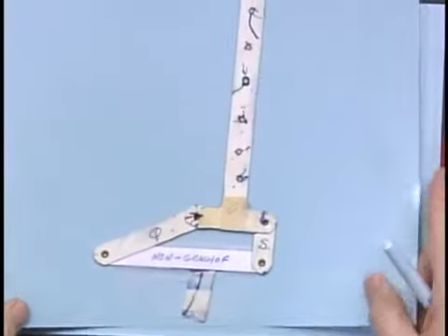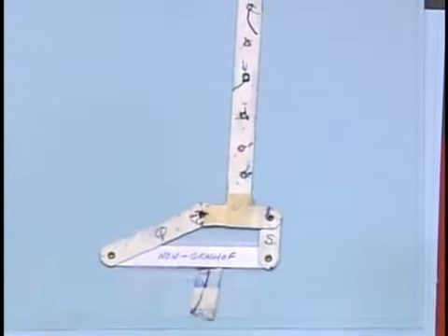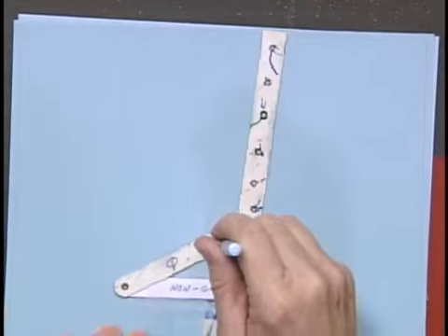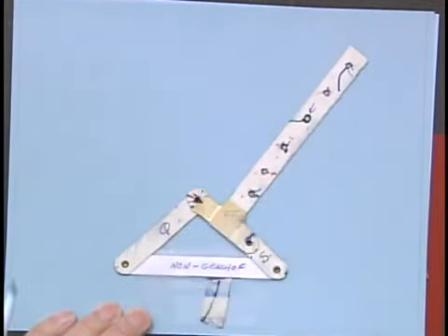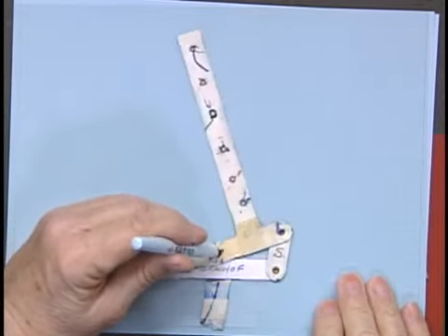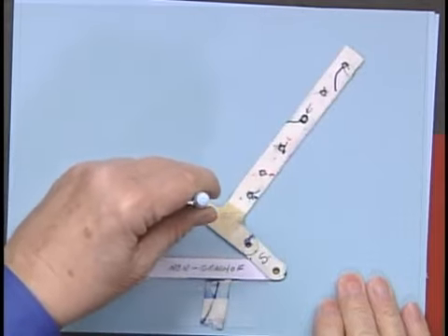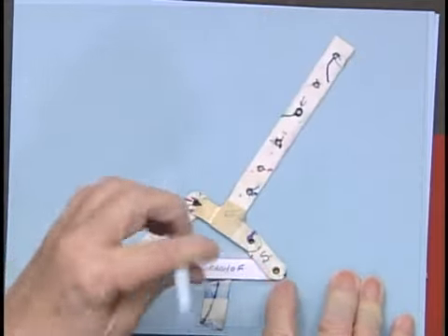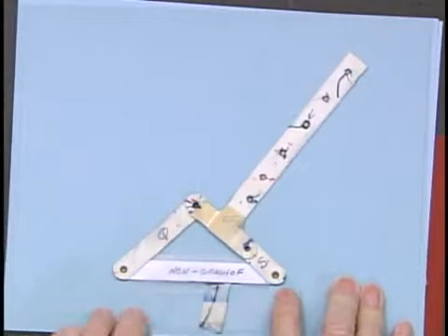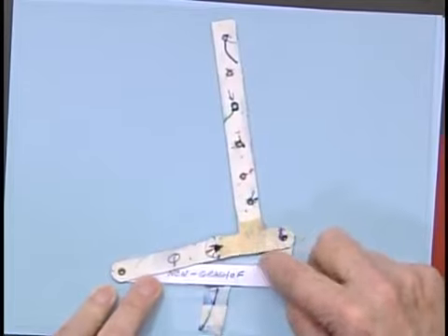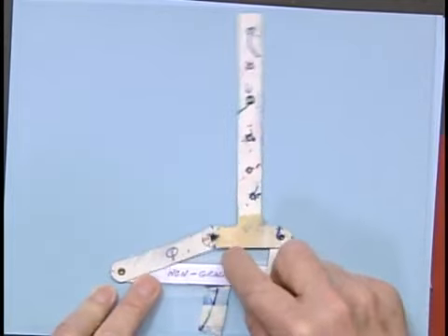Now let's take a non-Grashof linkage as an example, also made in cardboard, and see what we can do with it. Well, let's determine to your satisfaction that it is in fact non-Grashof. There, my hand's in your way, but if I do this with my non-dominant hand, you can see that I'm going to a toggle, so that cannot go any further that way, and if I go this way, it's going to toggle over here again. So I definitely have a non-Grashof linkage. I can't make a full revolution with any link.